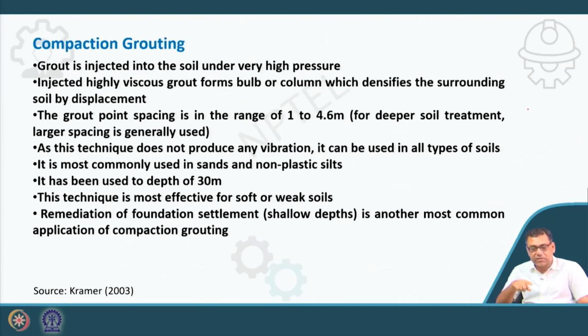But this last technique, compaction grouting, does not produce any vibration. So it can be used for any type of soil. It is most commonly used in sand and non-plastic silts. It has been used up to a depth of 30 meters. Okay. This technique is most effective for soft and weak soil also. Okay. The remediation of foundation settlement at shallow depths is another most common application of compaction grouting.